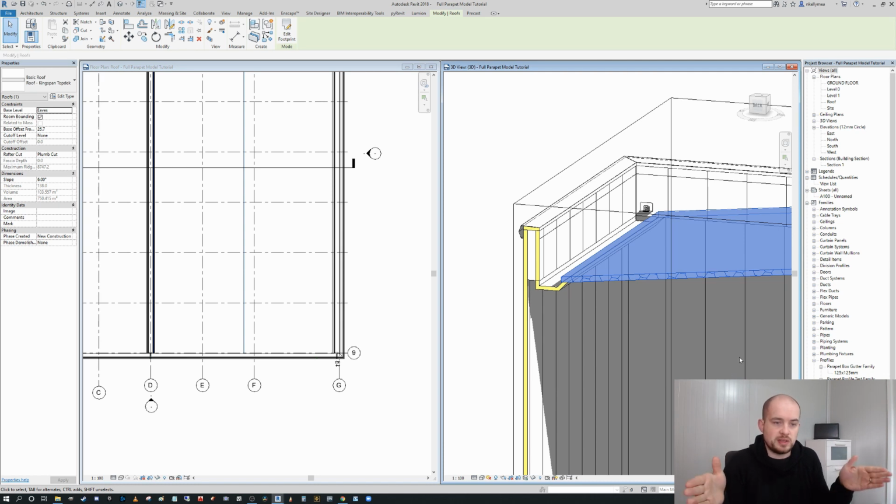If your building has to get a little bit tighter or a little bit broader, if you model this correctly, that is a 10-minute exercise tops to go around and just change the grid setting out for your structural, architectural, civil, and MEP models as well. If you have thought about the effects of what you are doing and how you can future-proof your modeling, your alterations are fairly straightforward.